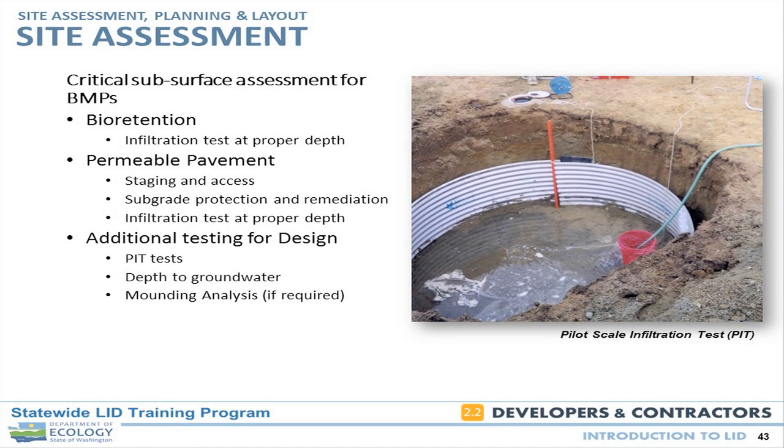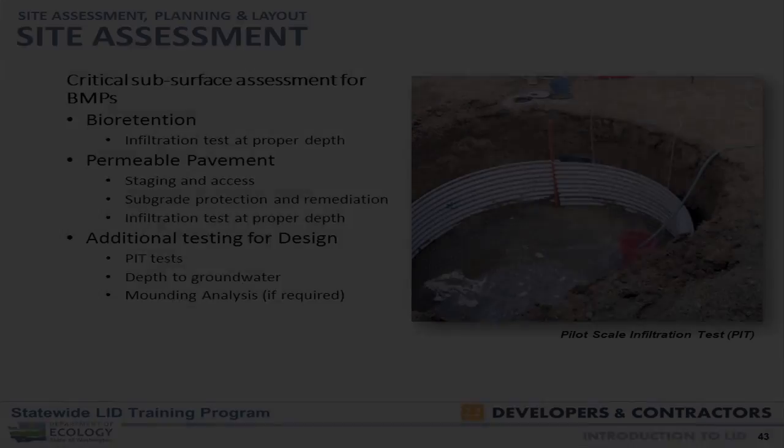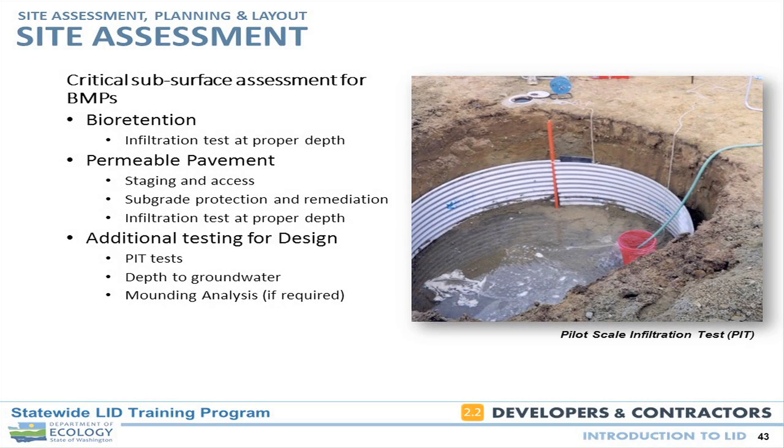I think, a bioretention area, you can pretty well know where they are. It's a discrete area. You can fence it off and say, look, let's not even excavate that area until we're ready to build the facility. Let's do our early rough grading and just leave that area ungraded for now so we don't foul it up. But the pervious pavement can be tricky. And so thinking ahead about, well, if we did a temporary construction access over here, we could do that. Or if we laid the site out a little bit differently where maybe something temporary could get located,